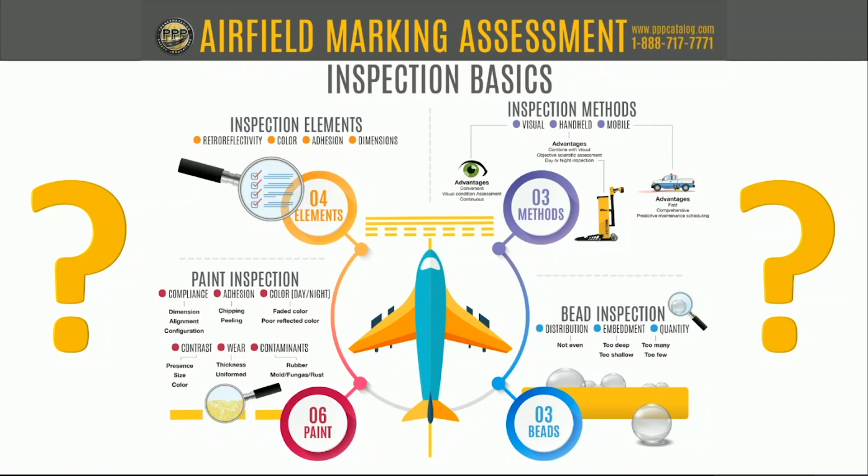Almost like a paint truck, and having a paint truck for the long line markings, the wider markings. That's what the mobile reflectometer is for, in my opinion, for periodic. And the Stripe Master 2 Touch, the handheld unit, is used for smaller markings, almost like you would use a small Graco for your smaller markings. That's when you use the handheld, and it's great for daily inspection.